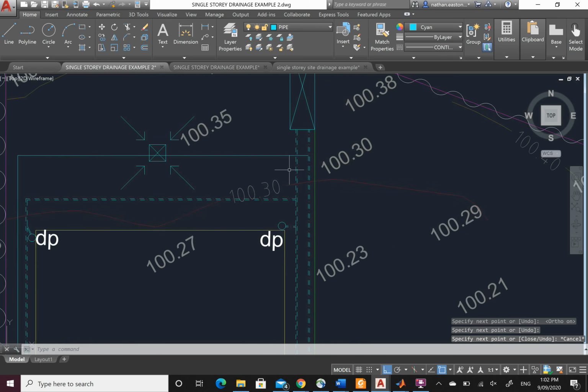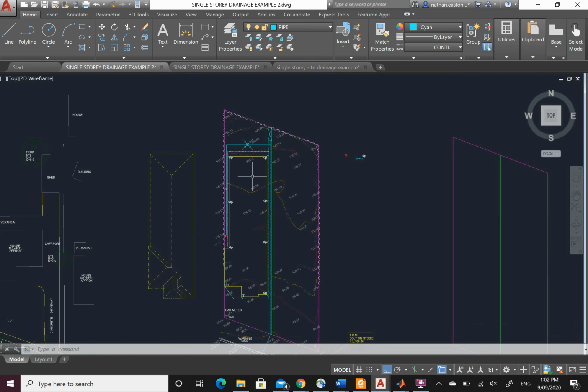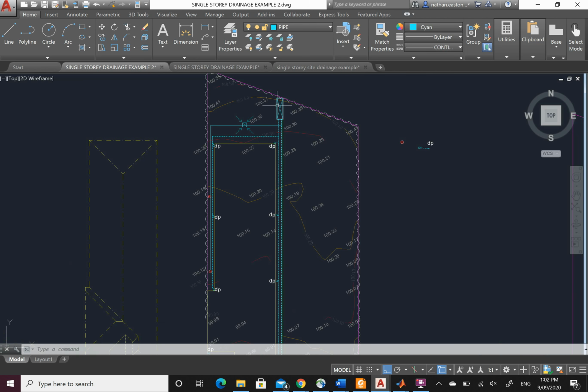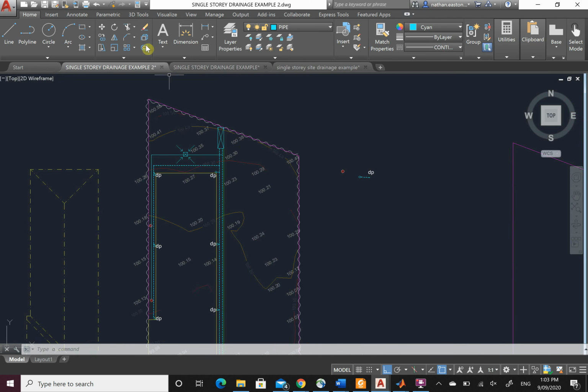Now, I know I said these pipes can never meet. So what collects on the roof doesn't meet the groundwater runoff. So collect it on the ground, discharge it straight to the street; collect it on the roof, to the tank, to the street. What we can do is the water that discharges from the tank, we can discharge our groundwater runoff to that pipe. This pipe falls away, doesn't fill the tank; this pipe fills the tank. So they'll never meet, which is good.